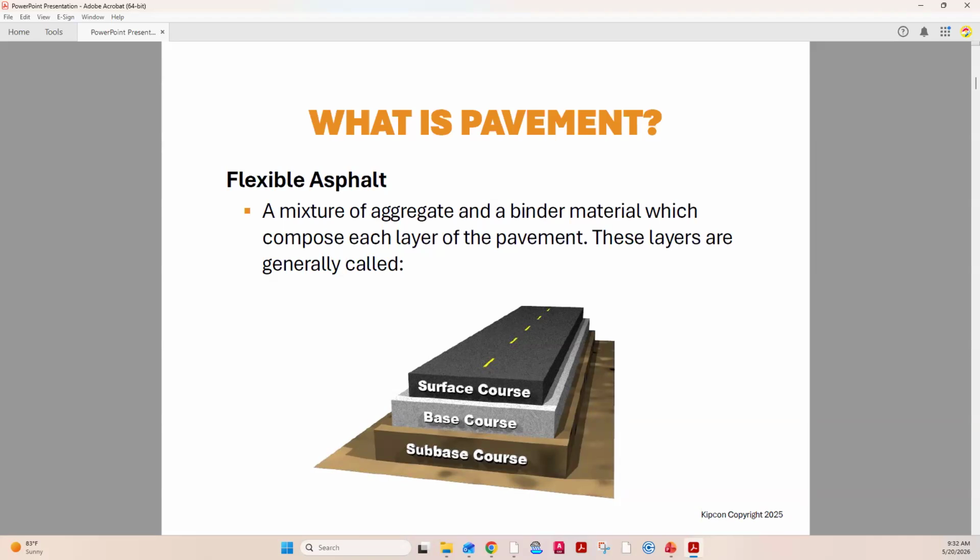Many times in New Jersey and Pennsylvania, that subbase course is what's called a dense graded aggregate, a DGA, or in Pennsylvania, it's called a 2A, and sometimes it's called a QP, and it's got all kinds of different names. But the important thing to remember is that it is an aggregate course and it's compactable so that it becomes almost waterproof and it's very, very stable.